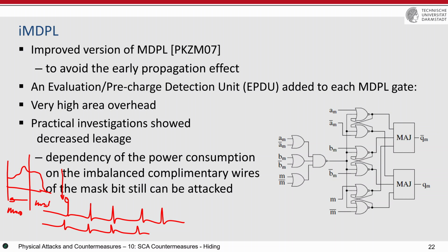Then you categorize them. You say, consider only those traces that have the same M, and perform the attack on these traces or on these traces for this cycle. For the next clock cycle, you have to do the same and categorize them, because M changes differently every clock cycle.